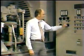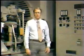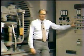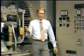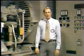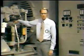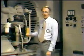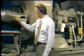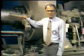You have seen in the 4 previous lessons of this module that the electrical system controls the major functions of the engine. It is in fact the components in the electrical system that time, monitor, and activate other components into operation at the appropriate time in the sequence. For example, it is the electrical system that monitors oil pressure during the engine start sequence. And it is also the electrical system that activates a pilot control valve which allows the variable vanes to open and close. Now, each of the systems on the package is monitored or controlled by the electrical system.